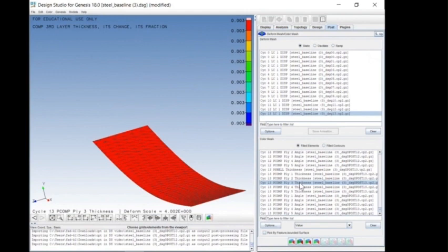Those are the elements with the orientation of the fibers at 0 degrees, i.e. running lengthways down the structure. Those are the ones which are going to contribute most to the stiffness, looking at the deformed shape of the structure. And then our angles didn't change. They're -90 still, -45, 0, 45, 90.